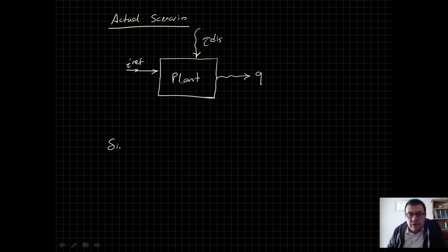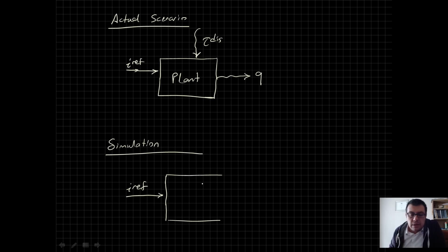And in simulation environment, what you need is this. You're again giving the reference current to your system, IRF, but this black box here is a well-known structure. If you recall, actually, it's nothing but multiplying with K nominal, right? Because the reference current is being multiplied with K nominal to give us the torque input to our system.